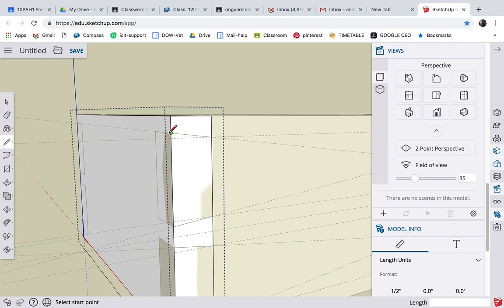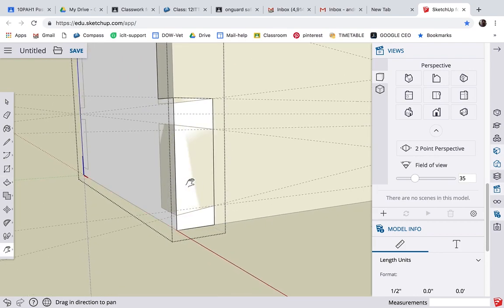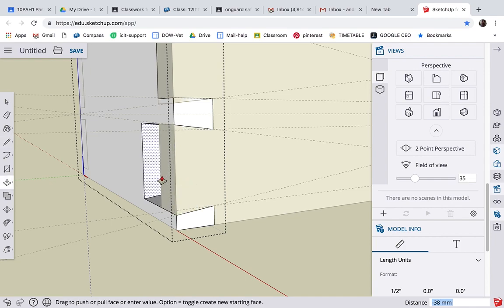You'll notice I've opened the end in edit mode. That's got the box around the outside. I'm going to click from there to there, from there to there, and now when I push pull, you'll notice it actually opens up and creates the pins. Move up a little bit, and line tool again, click once, twice, 3, 4, and again push pull.